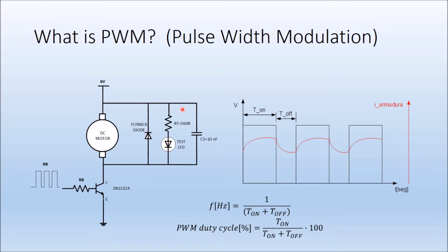And I also used in these circuits that I will show you next an LED which will dim according to the level of duty cycle, and a transistor here, and a capacitor that I use to eliminate noise, because these small DC motors that I will use for testing these PWM circuits are very noisy, so you need a capacitor to eliminate the noise. Otherwise, if you have digital circuits here, the noise could make the circuit malfunction.